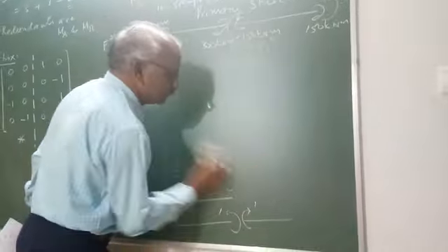For element number 1 it is L1 by 6 E1 I1 times 2, minus 1, minus 1, 2. This already we have derived. You have to apply this for span 1, so L1 equal to 10 meters by 6 EI. EI is uniform. Suppose EI is given as 2 EI or 3 EI, that you have to incorporate here. Here EI is uniform throughout, therefore 6 EI, 2, minus 1, minus 1, 2.